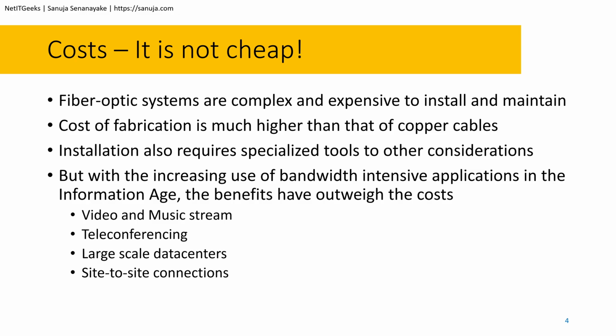But to meet the standards of fiber optic communication cables, you need to have really low manufacturing tolerances. So that's another reason why it is really expensive. Installation also requires specialized tools, and those tools have certain considerations that you need to take into account, such as the type of fiber optic cable and the grade of cables, etc. And the end connectors, for example, termination connectors, also slightly differ in how you use those fiber optic cables.